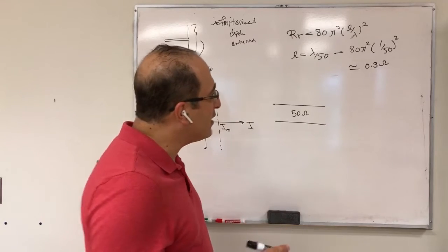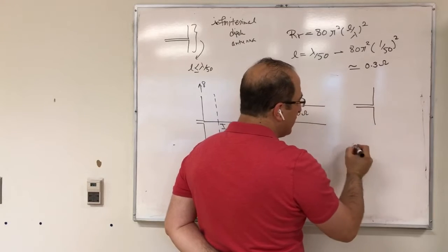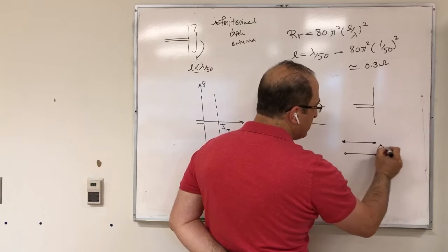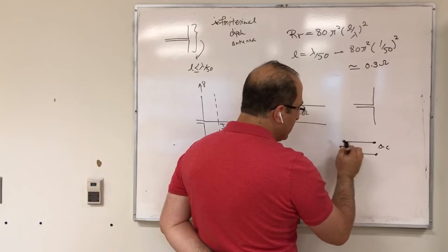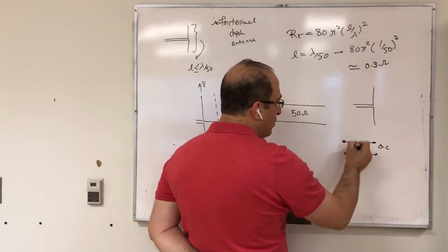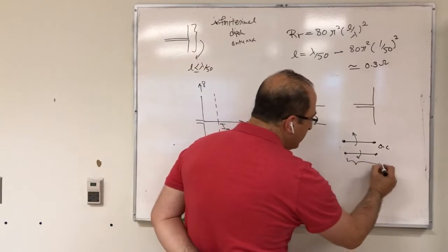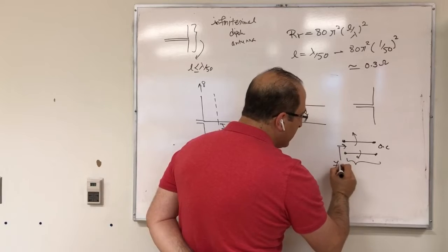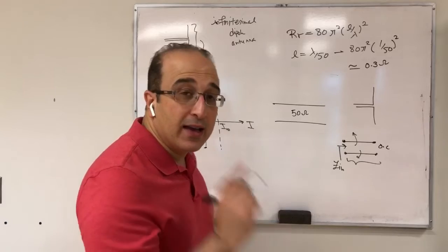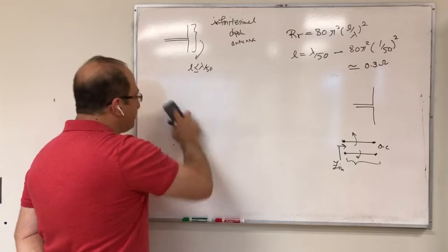The way to realize that: remember, this small dipole antenna was in fact an open circuit transmission line. This was open circuit, and then we started bending these arms upward and downward and made it an antenna. But if this is tiny, you can calculate the Z in of the transmission line, and it becomes a capacitance. Let me do it quickly.